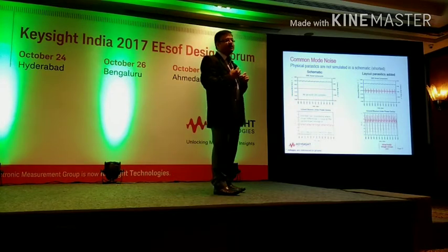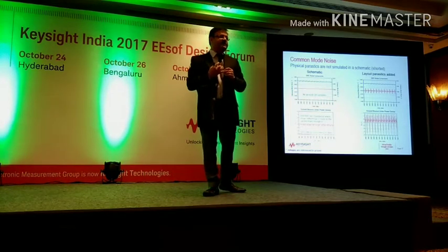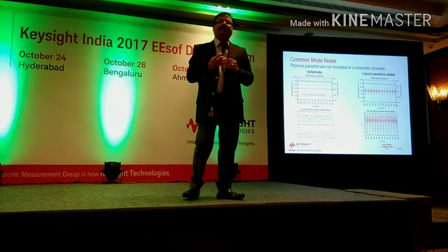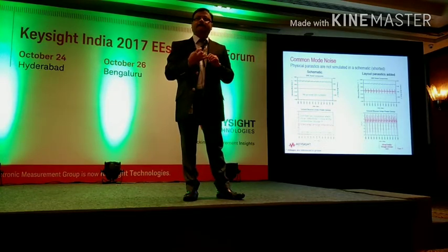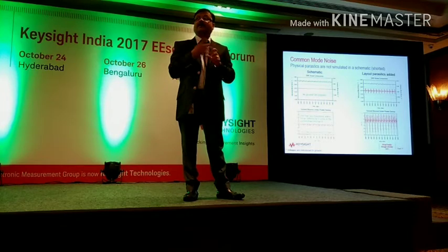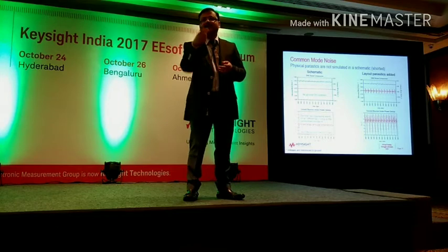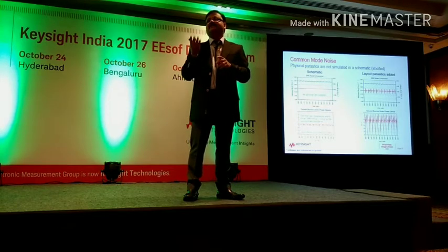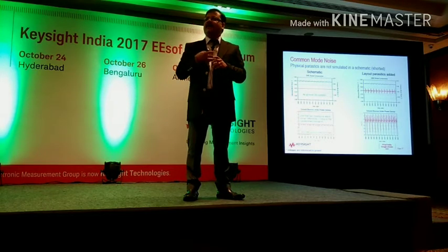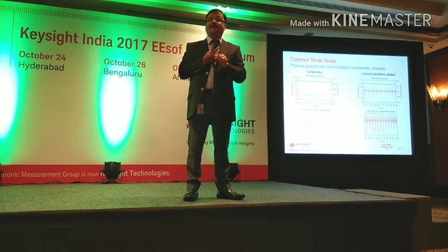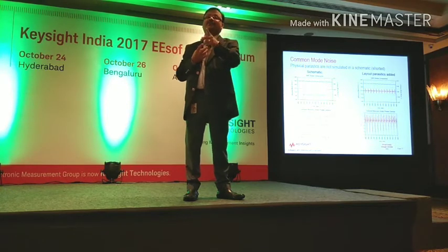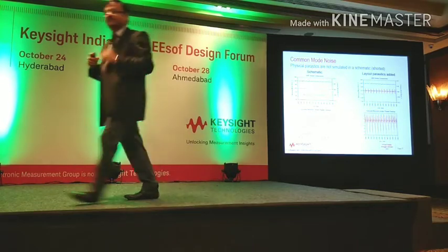Same thing is happening now slowly with power electronics. Do you know why? What's changing in power electronics? Higher inductive effects caused by switching frequency. Switching frequencies are going higher. Why? Because they want to reduce the size of the components. Absolutely, perfect. You deserve one.